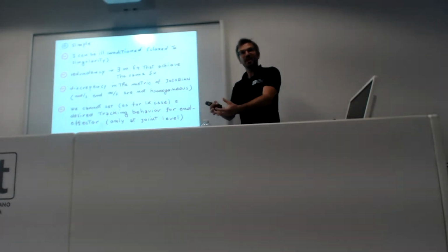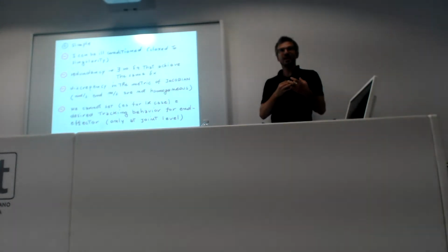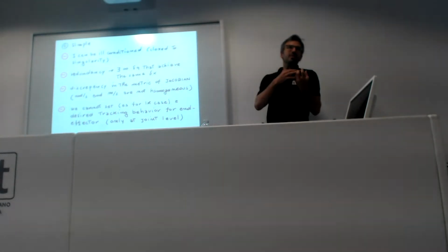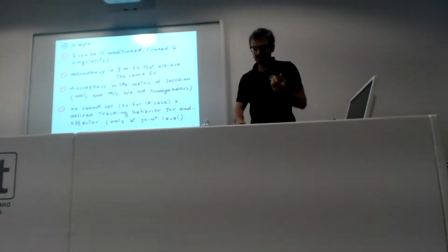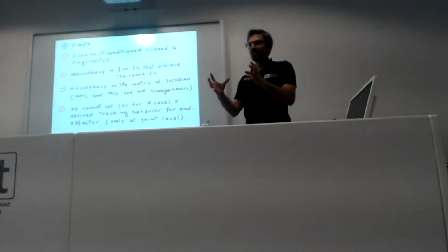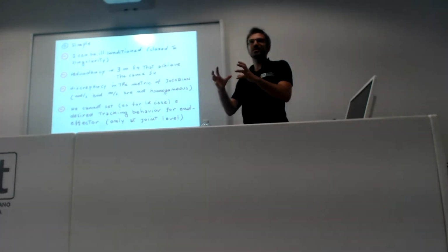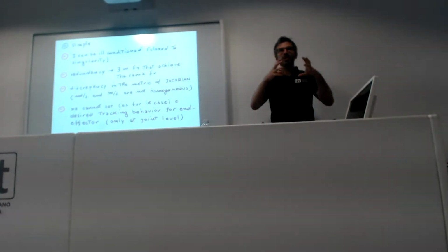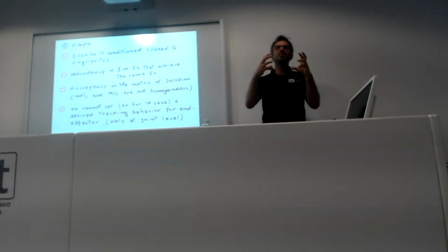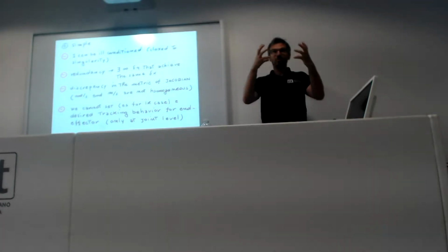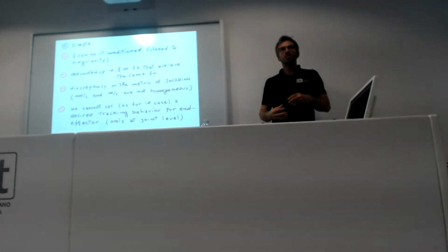And these dynamics, if we check at the end effector, will be reflected in a certain way. Even if you use, for example, constant proportional derivative gains at the joint level, at the end effector you will have a configuration dependent stiffness. It will not be a sphere, not isotropic, it will be an ellipsoid.